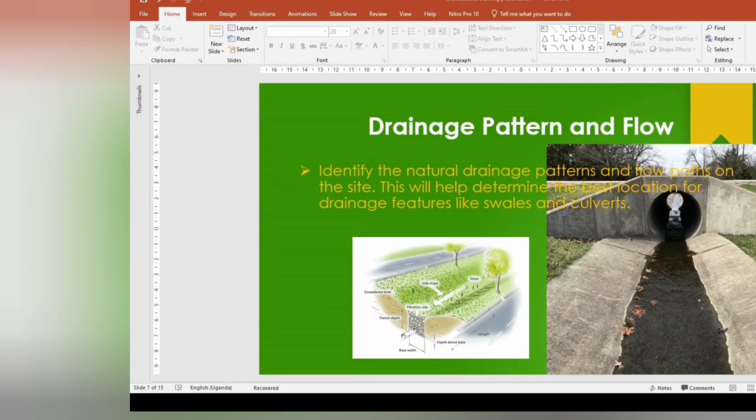So under foundation and footing, one should understand the house's foundation type. Before you start designing a plan for a client, you must first understand the type, depth, and footing to ensure proper water management and prevent drainage to the structure. Then install French drains or a perimeter drain system around the foundation, collecting water and directing it towards a suitable collection point.